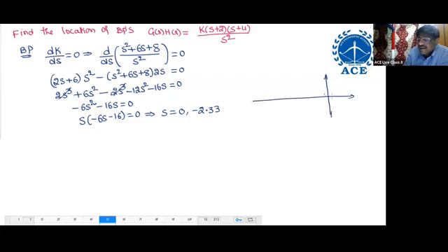So 2 poles at origin, 1 zero at minus 2, 1 zero at minus 4. Where are the root locus branches? Here no root locus branch. Here also no root locus branch, because if you take a point here, no root locus branch. But here if you take 1, 2, 3, that means here root locus branches exist. At 0, multiple poles are there. 100% it is a breakpoint. What is the definition of the breakpoint? Two or more poles directly located. No doubt it is a breakpoint. That means breakpoint 0 is correct.